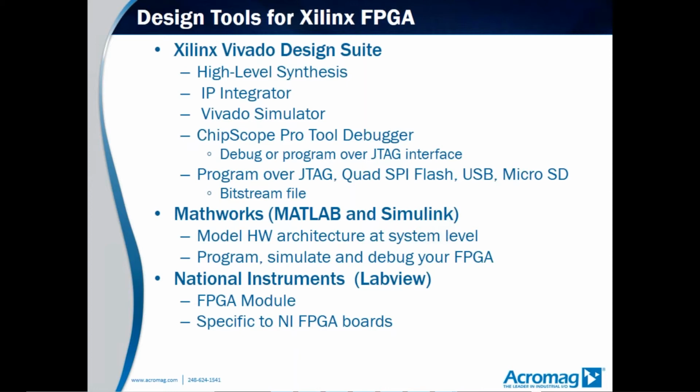Typically, you program your FPGA over a JTAG connection, through a quad SPI flash, through USB, or micro SD (secure digital). And this programming comes through the bitstream file. There are other tools that support Xilinx. There's a company called MathWorks that offers MATLAB and Simulink, and these tools allow you to model the hardware architecture at a system level and then program, simulate, and debug your FPGA. Then there's National Instruments, which has LabVIEW, and they have a tool called FPGA Module, and this allows them to program their FPGAs that are specific to the National Instruments FPGA boards.